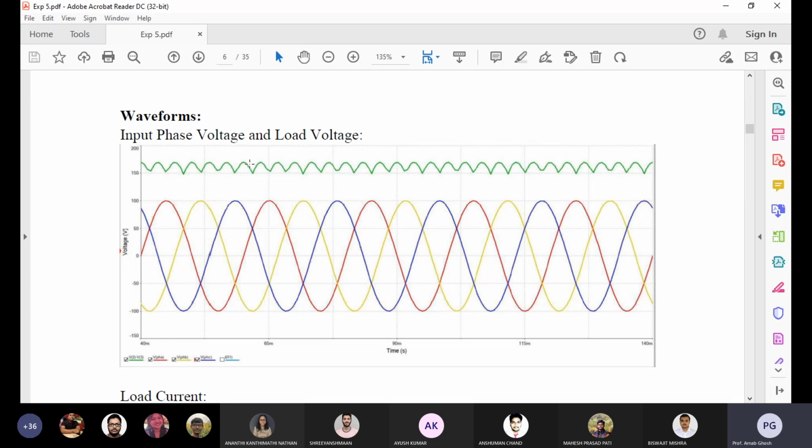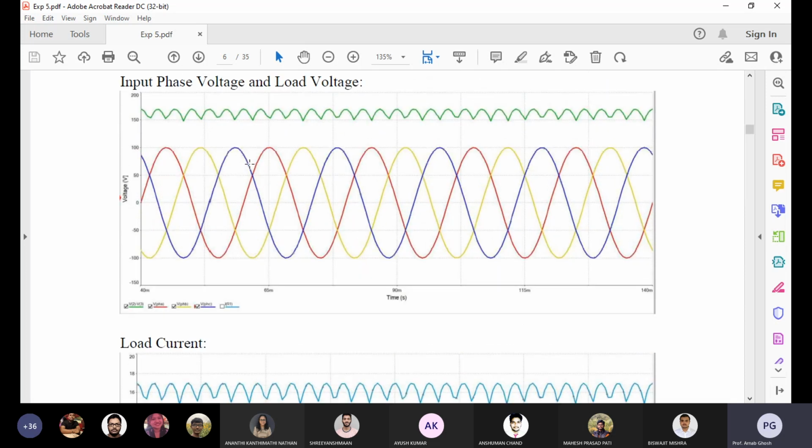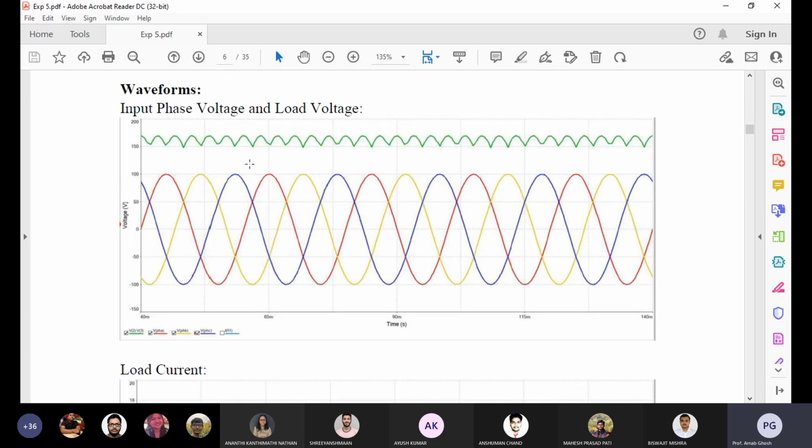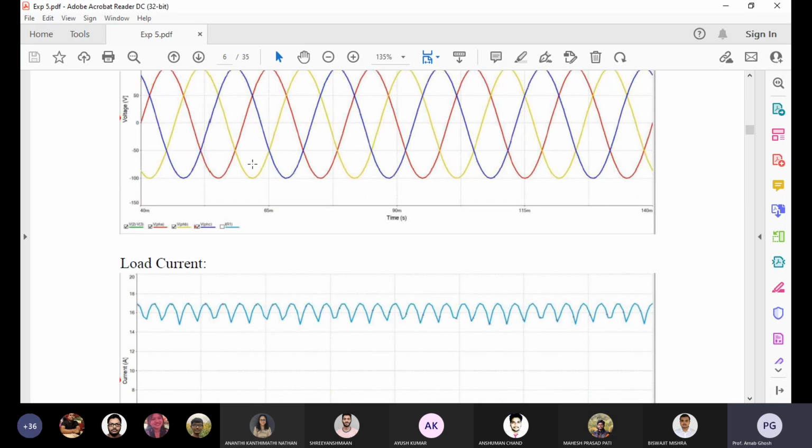Since the ripple frequency is more, a lesser value of capacitors is required, so costing will be less. But the voltage is more, so the voltage level can also be an important issue. In this case, it's not a huge change of the voltage, but still a good change, and the voltage level will be more for the capacitor, but the capacitor value will be less.